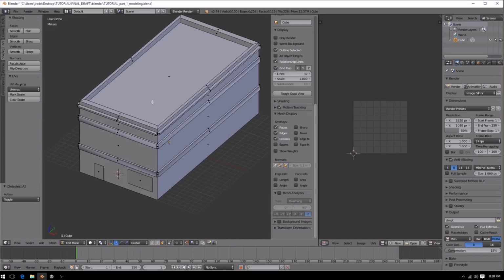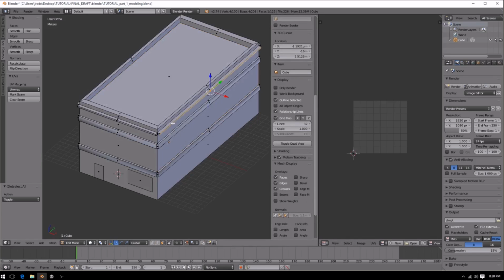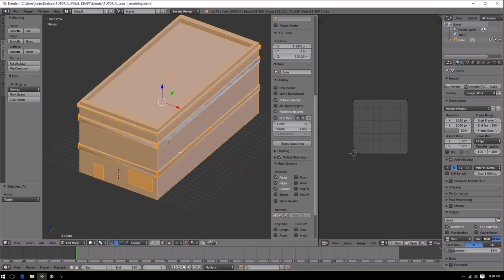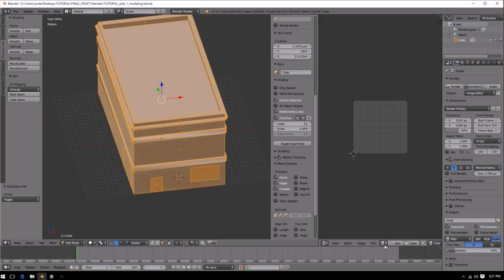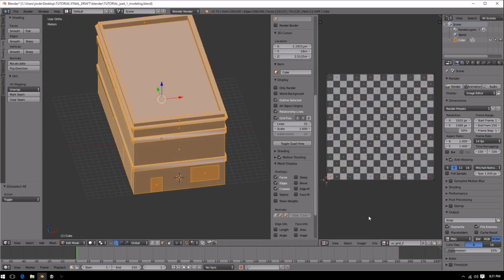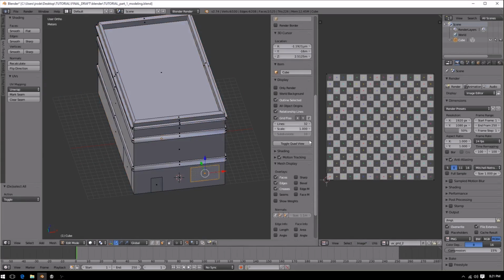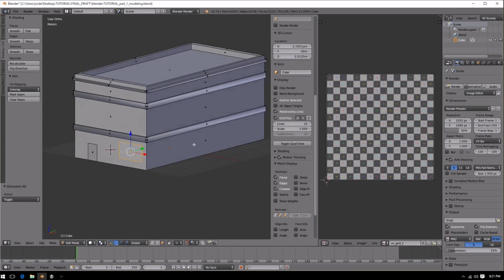So one thing I noticed is when we clicked on these things, we haven't assigned these pieces of our model to that actual texture yet. So an easy way to do that is go over to your model and make sure that your mouse is always in the work area that you want to be in, because if you're over here, it's not going to work if you're trying to affect something here. So click A and select the entire model, and go down here and just select your UV grid 2, or your UV grid 1 if you did it correctly. And so now when we click these individual items, everything will be on our same UV space, your UV grid 2. And again, this is just a test grid. We're just using this for Blender purposes.